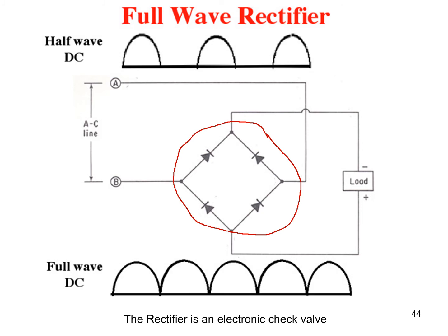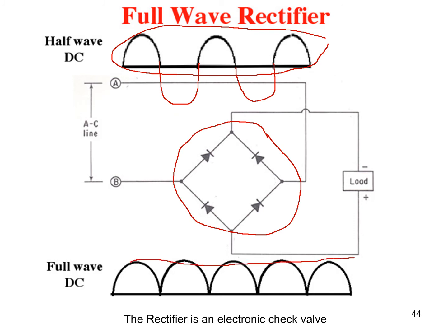And so we wind up with this, as you see in the top, where all the negative part, remember this is going positive, it should have continued here like that and gone down, and you'd get this nice little wave, but we cut off all the negative part. We only have the positive part, and then we also smush them all together. And you're thinking, well, this isn't quite smooth. If it were just one voltage, you'd want it to go like that. But as long as it's positive, it's close enough.